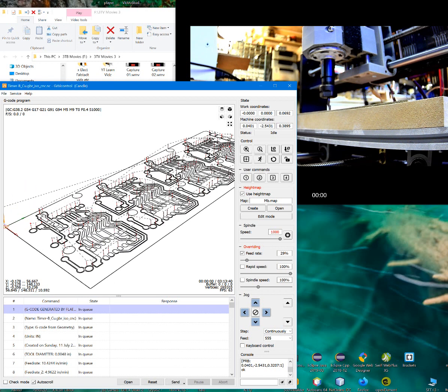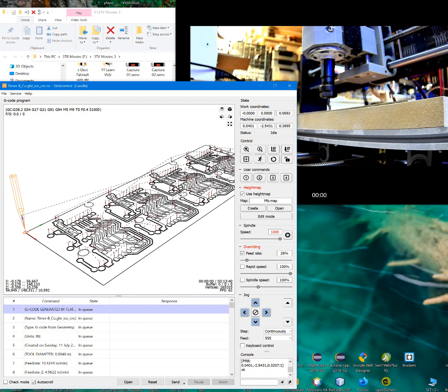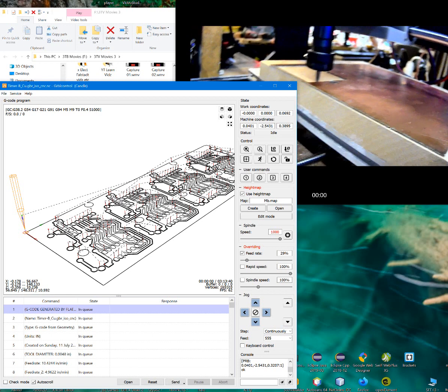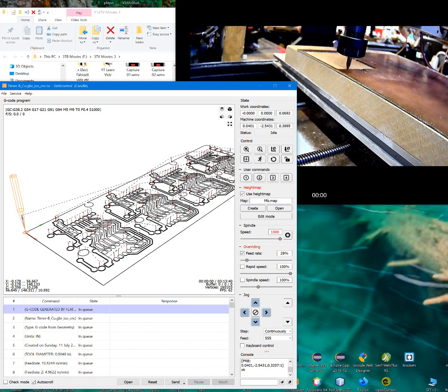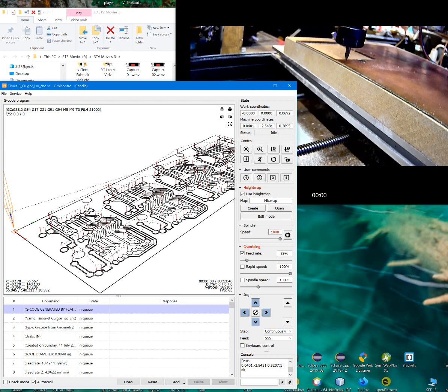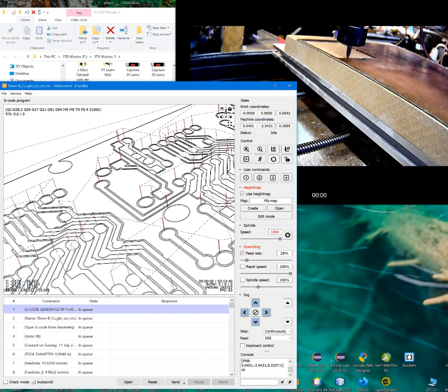And again, this is the one that's way more intricate. The thing about it is that I'm not really sure if this board comes out perfectly, I'm still not even sure I can use it. I'm not sure I can solder this without there being a ton of bridges, particularly in these traces that route between pads.